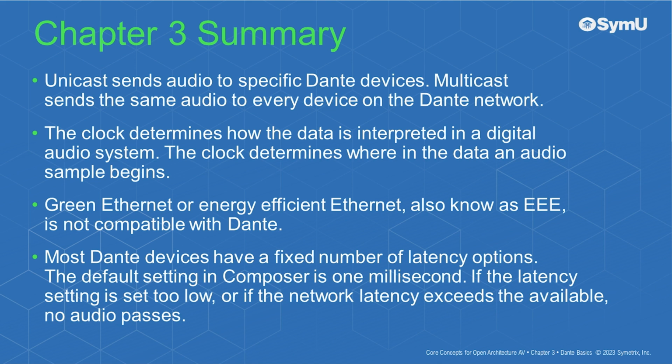The clock determines how the data is interpreted in a digital audio system. The clock determines where in the data an audio sample begins. Green Ethernet, or energy-efficient Ethernet, also known as EEE, is not compatible with Dante. Most Dante devices have a fixed number of latency options. The default setting in Composer is 1 millisecond. If the latency setting is set too low, or if the network latency exceeds the available latency, no audio passes.